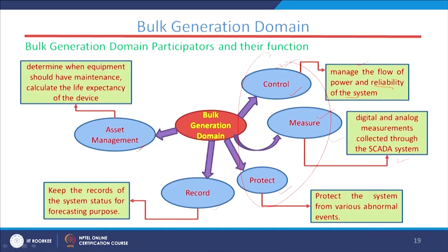This is also important, because as you know, without reliable operation, without any proper flow of the power, there is no question of standing of the power network, it will collapse. The power flow should be maintained properly, the generated power should be equal to power demanded, that is a must. To make the frequency constant at 50 hertz, the power generation should match the demand. If any mismatch is there, there will be fluctuation in the frequency. So, we have to be very careful.